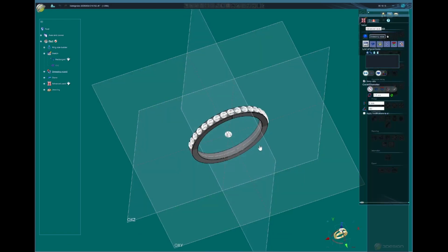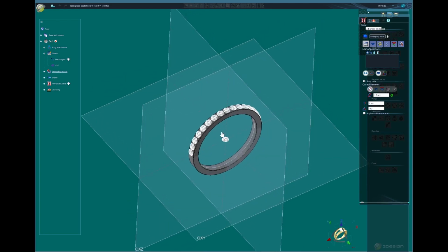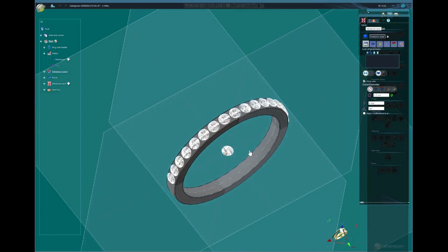Usually I do my prongs depending on, of course, the size of the stones, but usually 0.7 millimeters, 0.8 millimeters. 0.7 is more what you are going to use, or at least it's more what I use. I design with 0.7 millimeters. Okay, so we click over here. We want 0.7 millimeters prongs.